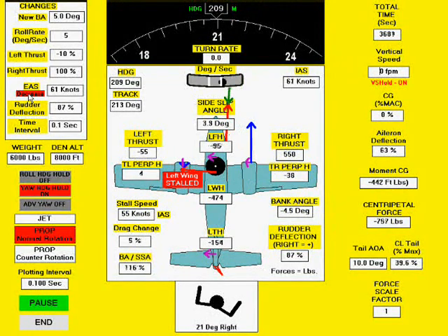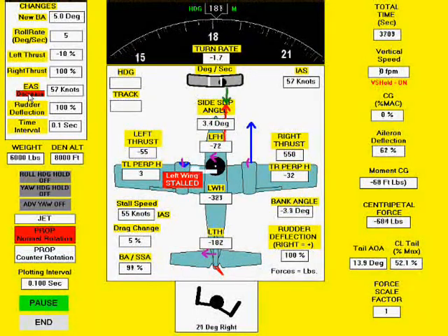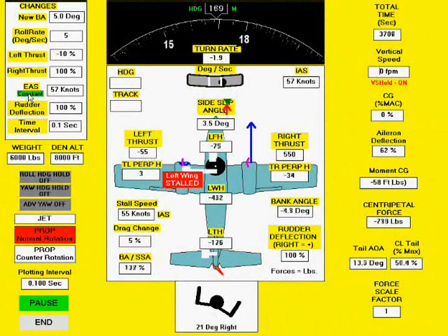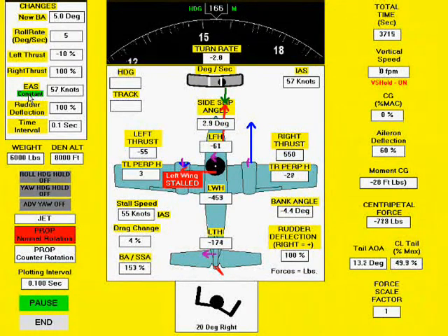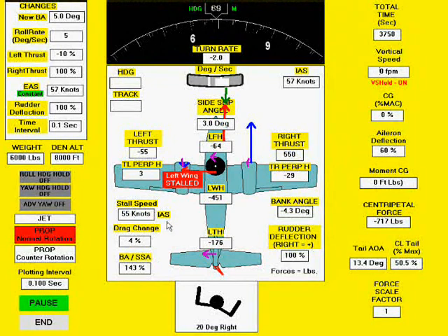Before reaching full rudder deflection, the left wing stalls and a spin entry begins. What happened? We are apparently above our previously observed stall speed of 55 knots, but stalled before reaching full rudder deflection. The problem is that VMC is lower at high density altitudes, and indicated airspeed can be significantly inaccurate at high angles of attack. The correct stall speed in this case is 61 knots.